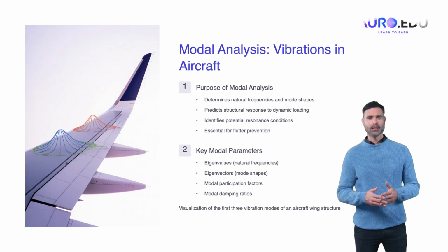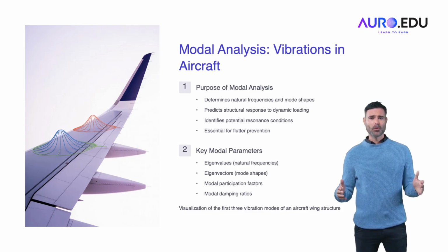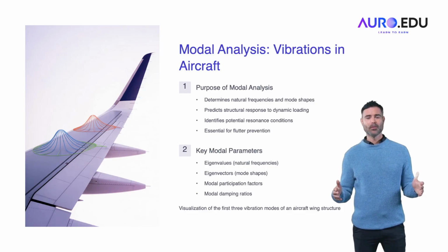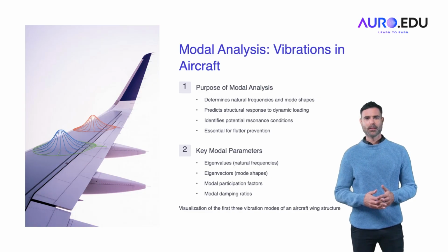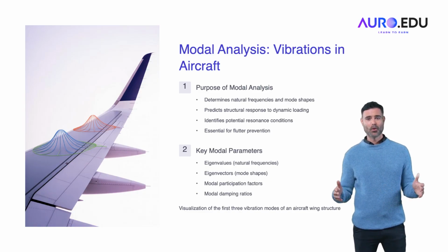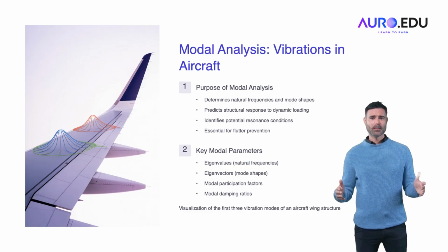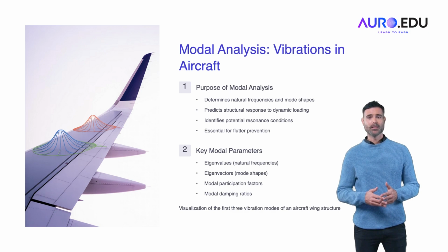Modal analysis, vibrations in aircraft. Modal analysis is used to determine the natural frequencies and mode shapes of aircraft structures to predict their response to dynamic loading. Eigenvalues represent the natural frequencies of the structure, while eigenvectors describe the corresponding mode shapes of vibration. These analyses help predict how structures will respond to dynamic loading, such as turbulence, engine vibrations, or control surface deflections.